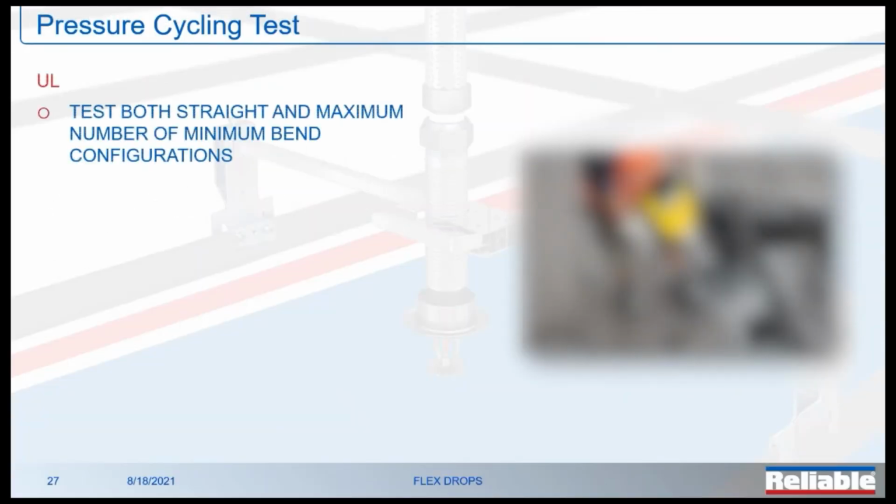Pressure cycling. So this is kind of the water hammer, right? We're going to pound this thing with water hammer over and over and over to make sure that those minor shocks that happen over and over and over don't damage the product. So at UL, we're going to test it in its straight condition and with its maximum number of minimum bends.